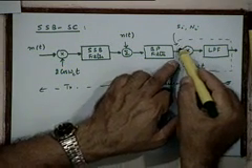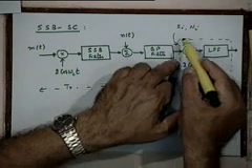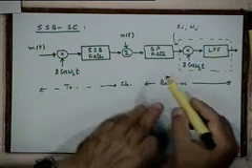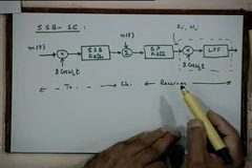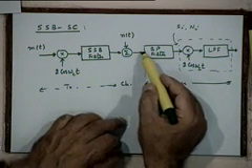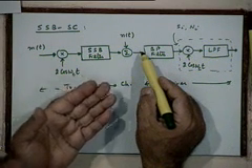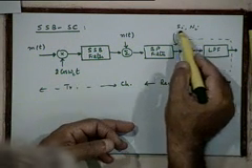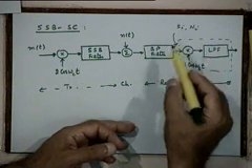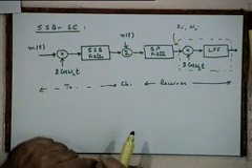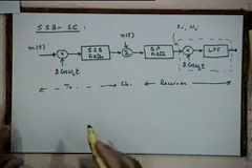It is more useful to talk about the input signal and input noise powers at the output of the band pass filter, the front end filter of the receiver, because at this point the input noise power is infinity. So it's much more meaningful to talk about the input signal power and the input noise power immediately after the band pass filter. That's what we have been doing. So